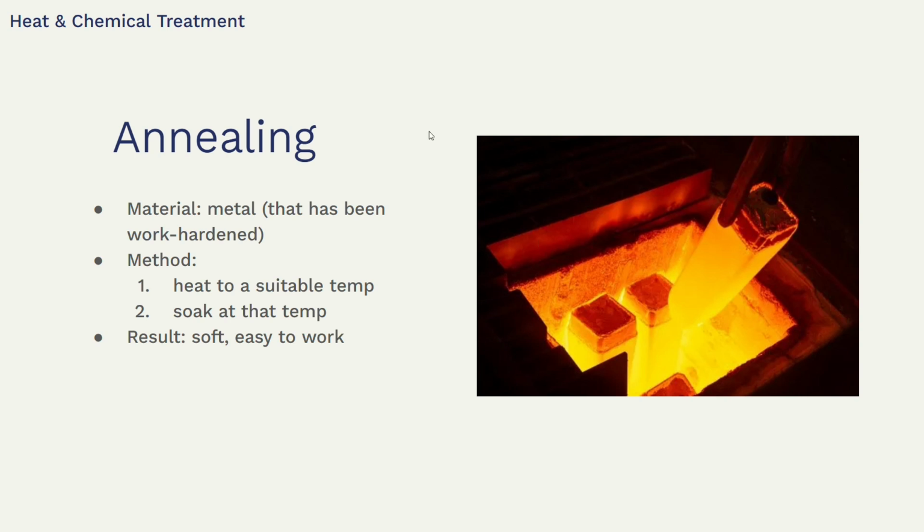Similarly, we have annealing, and this is done on metal that has been work hardened. We do this by heating it to a suitable temperature and leaving it to soak at that temperature. The result is a soft and easy to work with piece of metal.